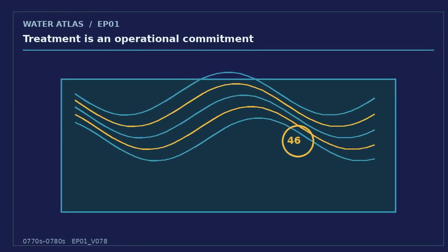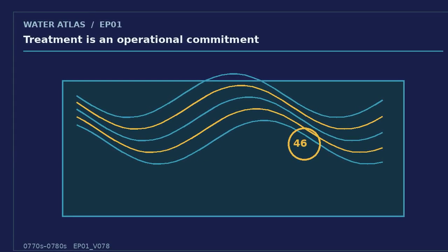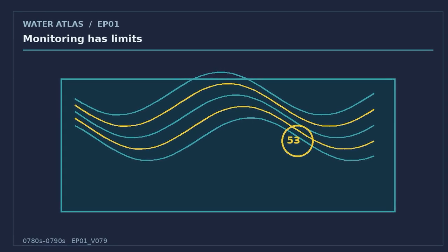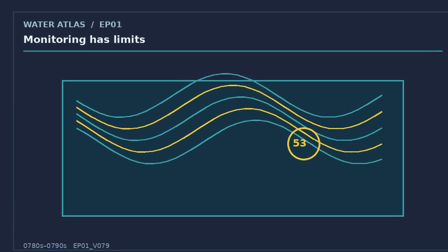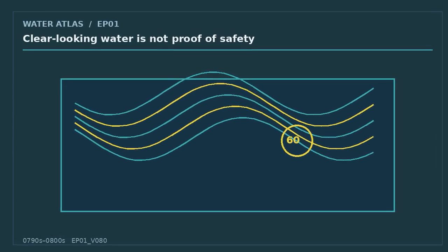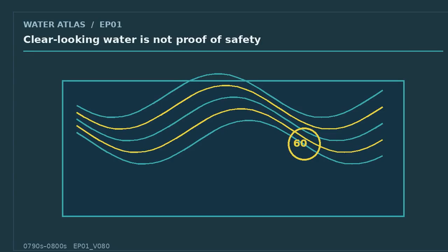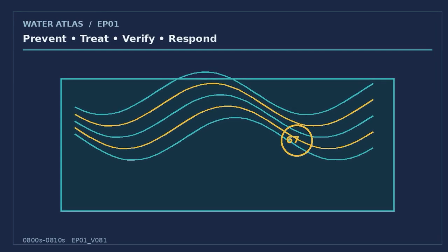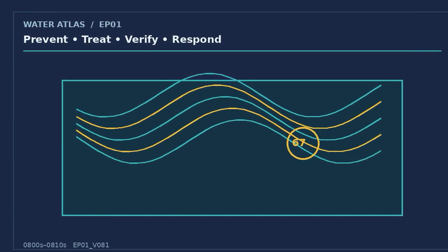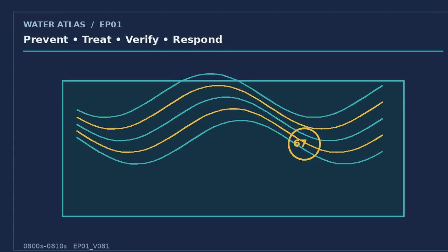Fifth, examine failure modes. What happens if a pump stops, a screen blinds, aeration fails, a clarifier bulks, a membrane fouls, a chemical feed runs empty, a sensor drifts, or power is lost? The design should include alarms, redundancy where justified, bypass controls, operator access, safe isolation, sampling points, and a clear response plan. A reuse system also needs cross-connection control, labeling, storage management, and communication with users so that a quality excursion does not become an exposure event.